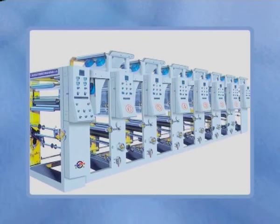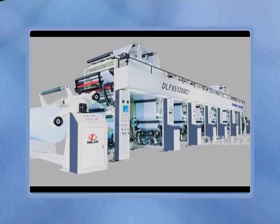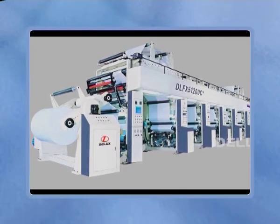Gravure printing is a photomechanical intaglio process in which the image to be printed consists of depressions or recesses on the surface of the printing plate. The process is the reverse of relief printing, in which the image is raised from the surface of the plate. The printer forms the image by cutting into the plate by hand or by using acids or other chemicals to etch the plate along the lines of the desired image.